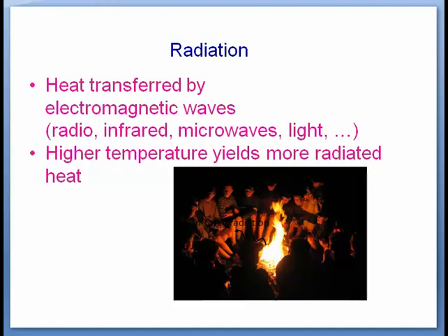The understanding of the modes of heat transfer is very important, because in a boiler or in thermal power plants, when the heat from the combustion of coal is transferred to the water that is moving in the water wall, first the heat is transferred through the water wall thickness by conduction, then at the inner wall surface and the water interface, the heat transfer is by convection, and throughout the fluid heat transfer is by convection.